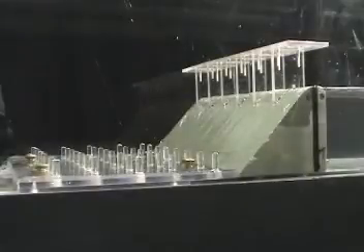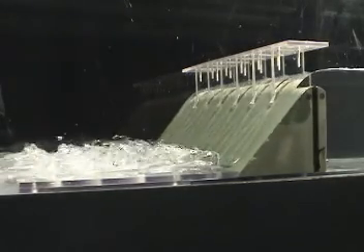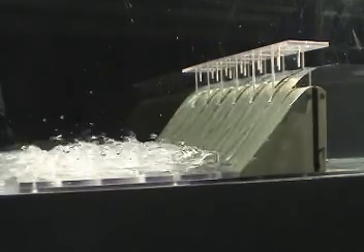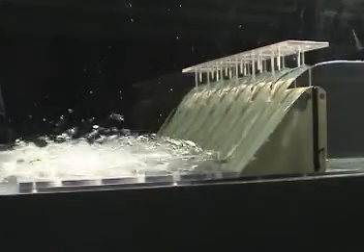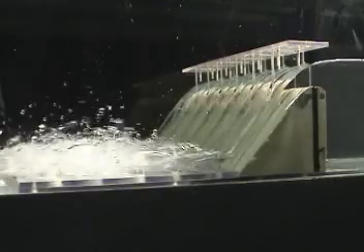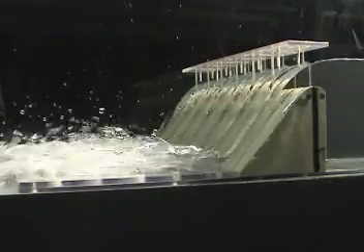In this experiment in a water channel or flume, the fast-moving supercritical flow downstream of the spillway causes erosion of the riverbed. In this flow, the Froude number is the most important dimensionless parameter to match between the model and the full-scale spillway. The Reynolds numbers don't match, but it doesn't matter.